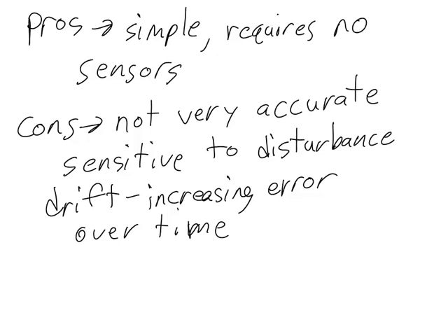If an external disturbance, like your finger bumping the slider, comes and moves the slider out of position, the controller is not able to compensate for that. And so the next time something else comes and bumps the slider, the error will increase, and over time the slider will become more and more out of position, and you will need to periodically re-zero the slider in order to get it back into position.